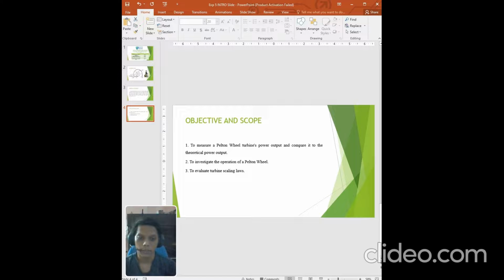By measuring the volume flow rate, pressure, rotational speed, and shaft moment, this experimental lab can calculate the turbine input energy and output power. Based on the data, we compute power input and output, as well as efficiency. To see the link between calculated variables, we can create a graph using a tabulated result, and we can add up the result and observation. That's all from me. Thank you.